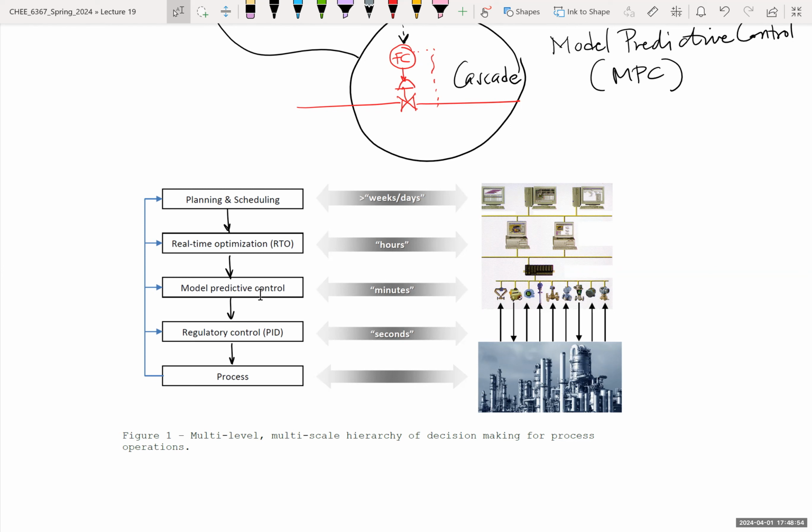There's nothing magic about it. It's just that the time constants and what is observed there are such that seconds for PIDs, minutes for MPC work well. In other systems like anti-lock brakes, the sampling period is much shorter. You may have 10 hertz sampling frequency, or even higher, 15, 20.